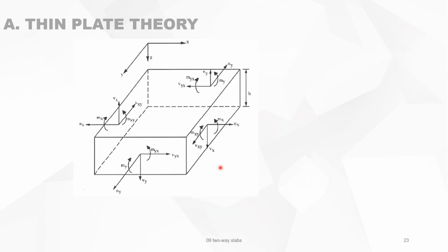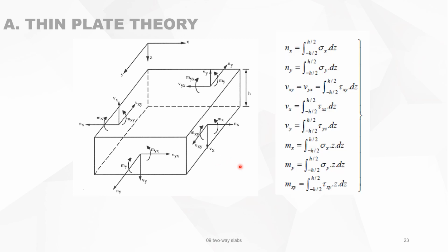You can convert those stresses into forces. For instance, the Nx force is a normal force on a part of the slab which is perpendicular to the x-axis. And this force Nx is nothing more, nothing less than the integral of the normal stress in x direction over the depth of the slab. This is an infinitesimally small distance, those two dx, dy.